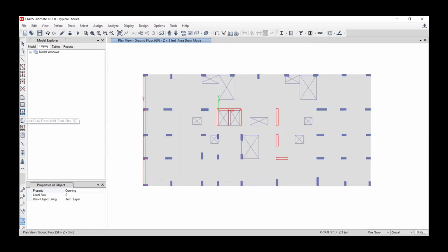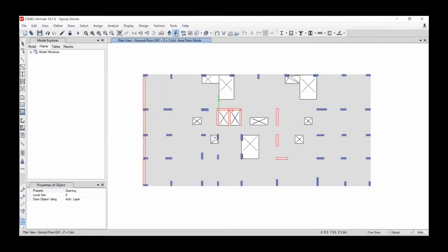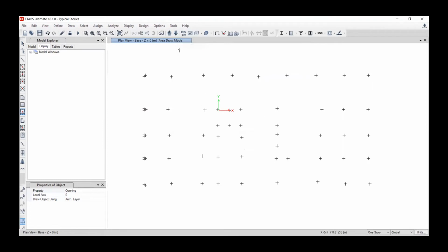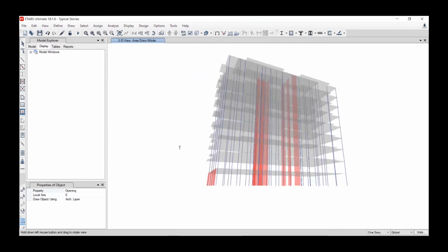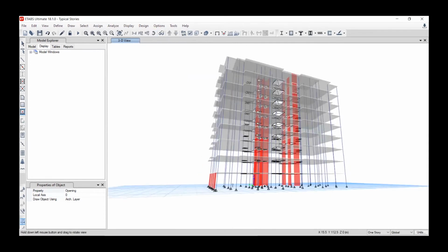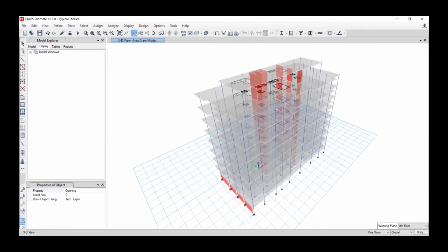So from here you can draw the opening for one story. Make sure it is one story, okay? Not be replicated in other stories, and select. So architect, select, and now we go down. Here would be the 3D view. We can see that the openings exist in the whole building, and we still have to do the roof.